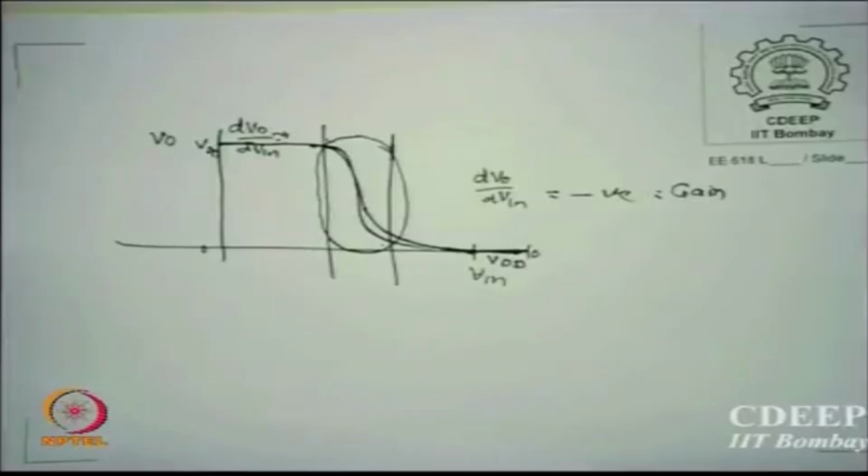So analog circuits only work in this small input range. That's why small signals, whereas digital can go from 0 to VDD. Okay. So gain only comes with very small inputs. So we are worried all the time about this region in the case of analog.